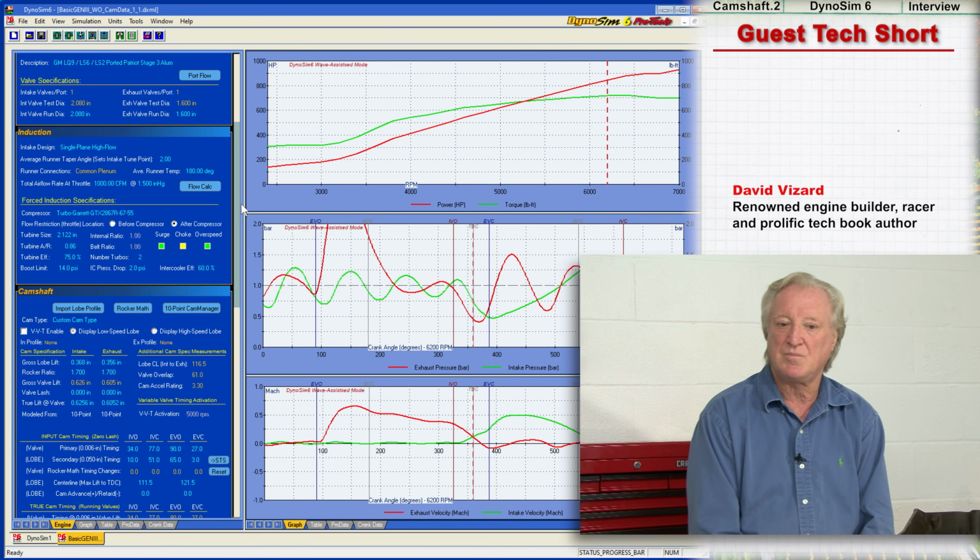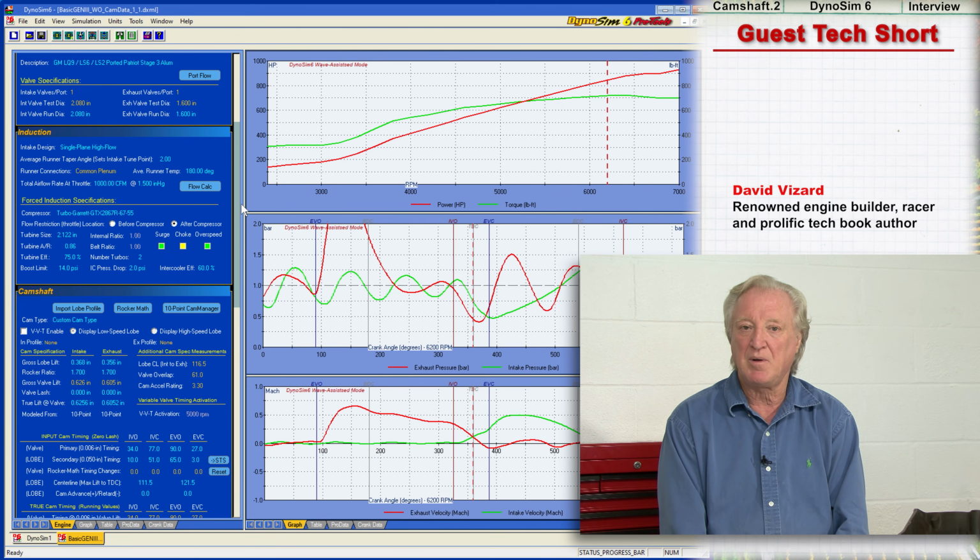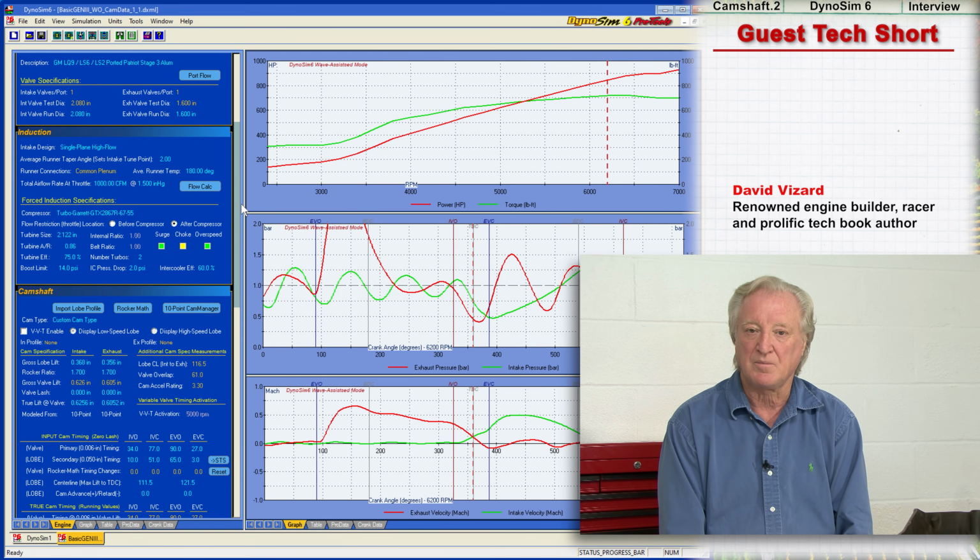If we deal with them separately, we can actually build a system that has 0 effect on horsepower. Here's what you do. First off, you make sure that the exhaust dumps into a resonator box which is of large volume, at least 10, 12 times the volume of one cylinder.